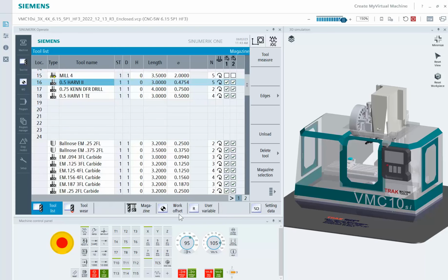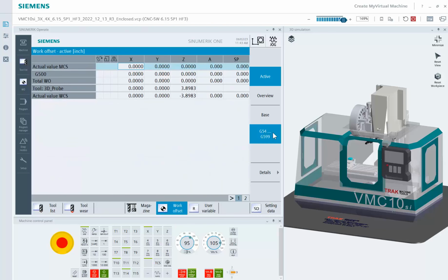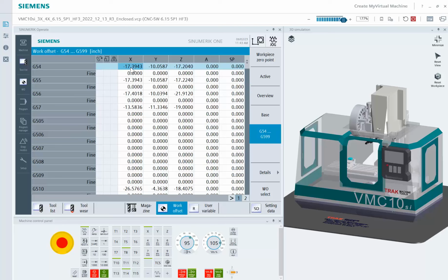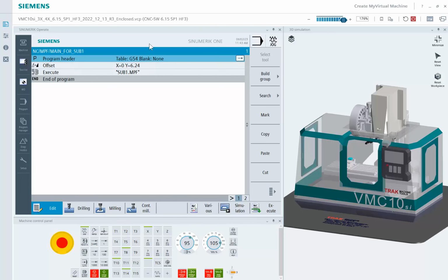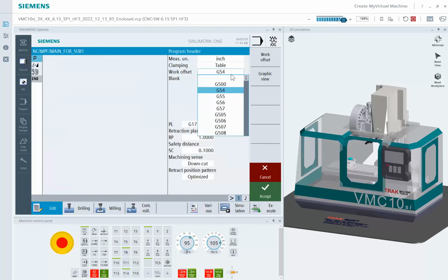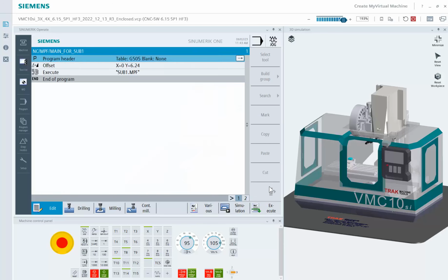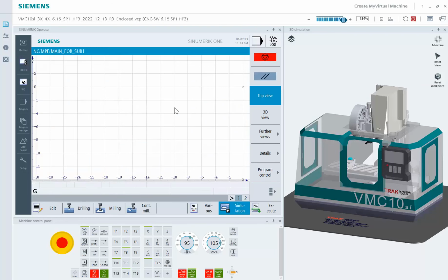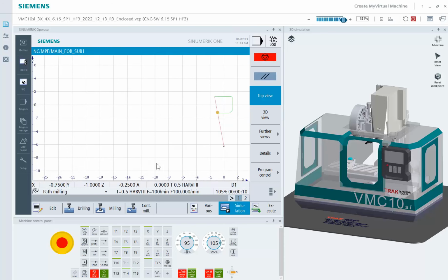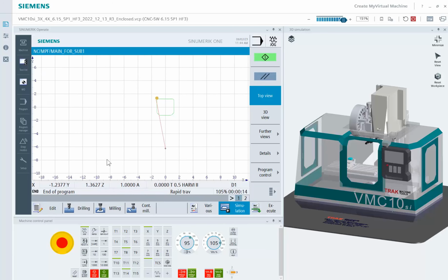So these are the little things that you might work through when trying to figure out if in fact it's working. So I'm going to leave my G54 alone. I'm going to switch it to 505 here. So at least this way I can use G54 for a previous, another job in case I want to get back to them again. So let's just go to 505. I know there's no values in there. I'll make sure that's not skewing my simulation, because the goal is that I see the part shifted up. I may need to have, there we go.